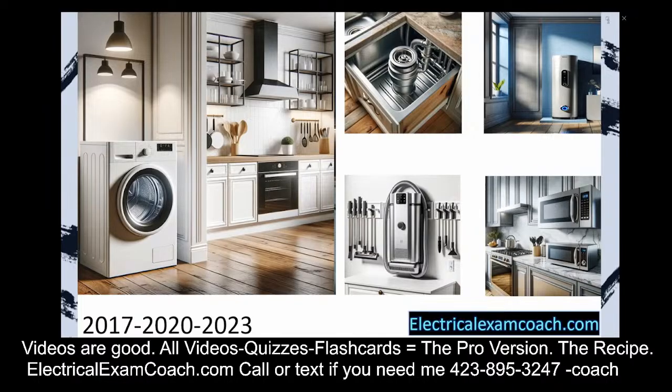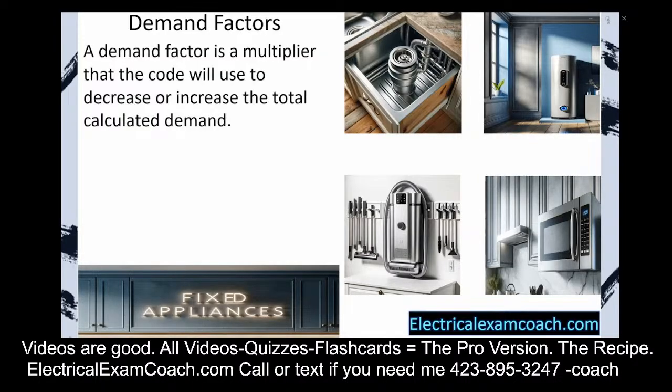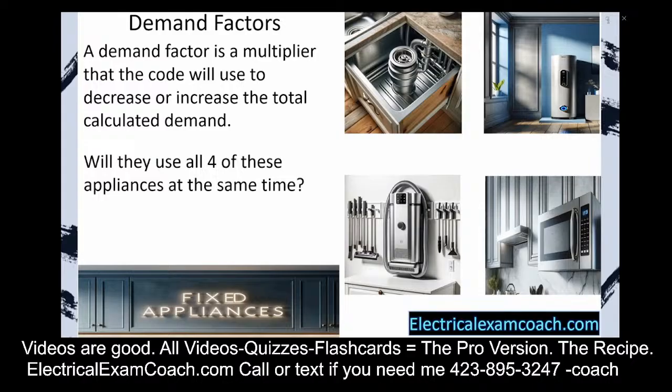Let's get to it. Before we dive into the calculations, let's learn about demand factors. We're going to be using them for the rest of the program. A demand factor is a multiplier that the code will use to decrease or increase the total calculated demand. The question is, will they use all four of these appliances at the same time? And the answer is no. So the code makers have made it so we can reduce the overall demand.